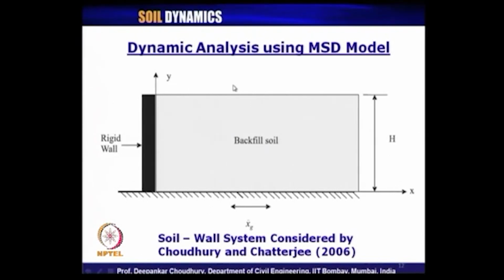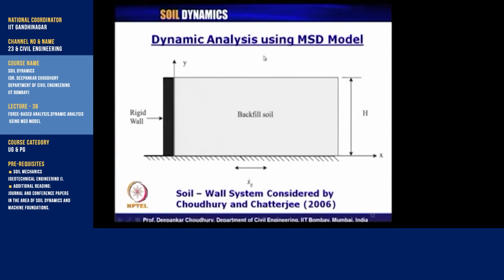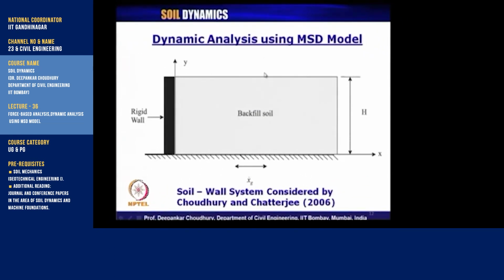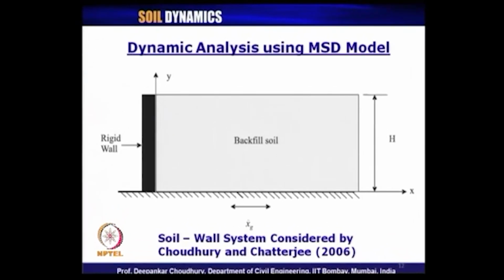And after a particular horizontal distance, when we found that there is hardly any significant change in the value of the displacement function, we can say that beyond that it is hardly having any effect on the wall. So, that is nothing but the way to compute the zone of influence for the estimation of this soil mass.